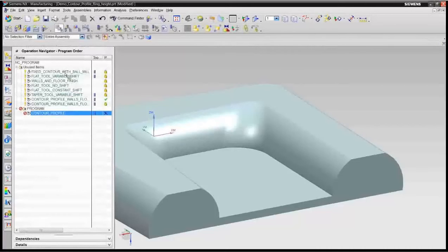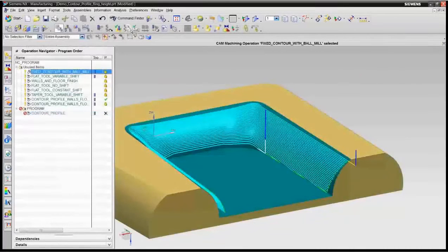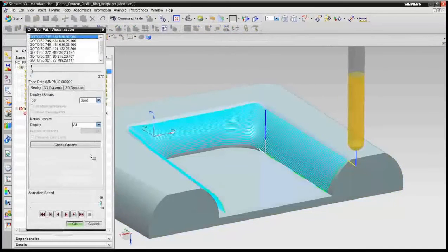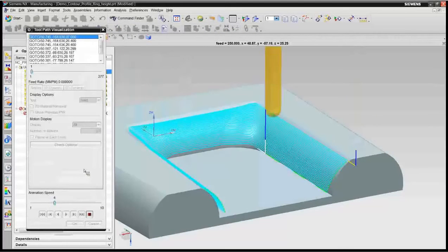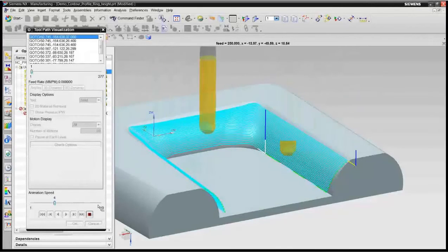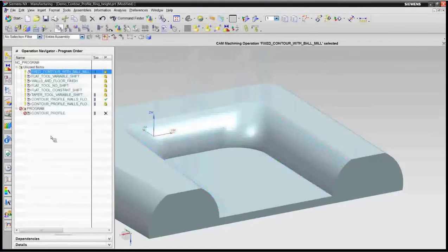And if you come in with just a ball, let me replay this and just kind of show you. The typical tool path that you'd do in the past was you'd machine this something like this with just a ball end mill. The time to do that is actually quite a bit longer. And so what we're going to do is use a contour profile operation.